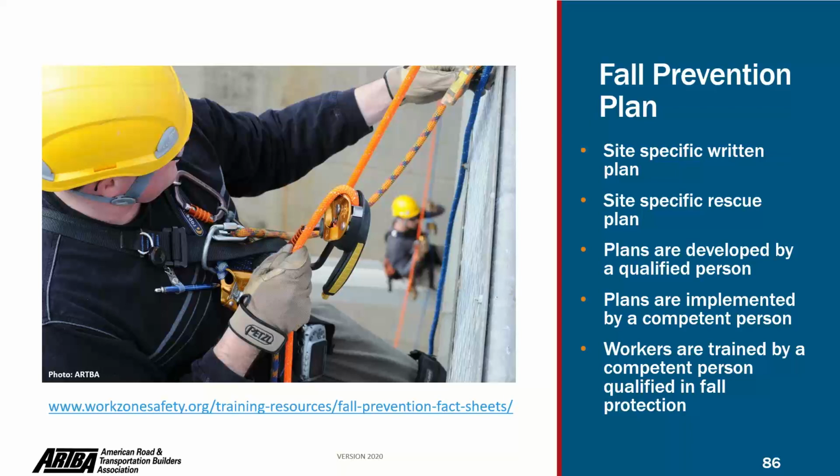It's important to have somebody going to the access zone of the work zone, okay? Because very valuable minutes are spent for the ambulance to find the access zone. They receive the phone call, they go to the place, they arrive at the place, but they don't know where to access the work zone. So that's important in the plan, to have somebody going to the access zone and provide instructions to any rescue personnel arriving, and take them directly to the location in which we have the victim. Okay, it's an important part of the plan.